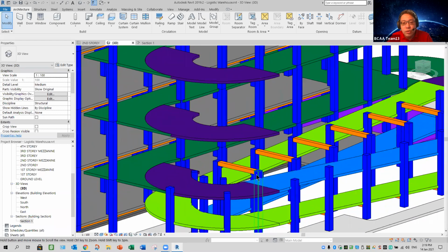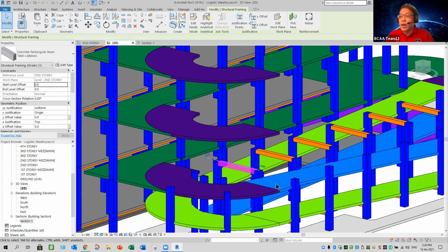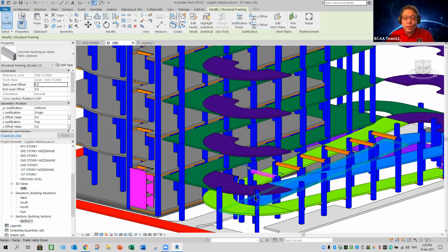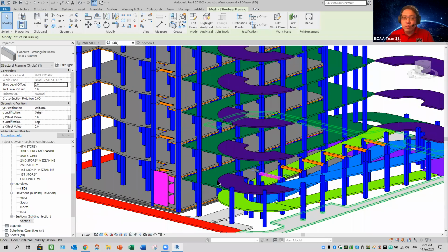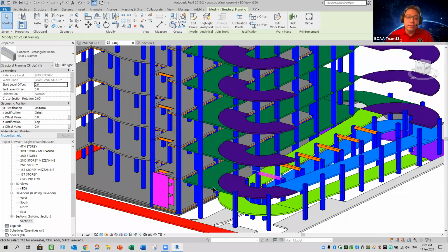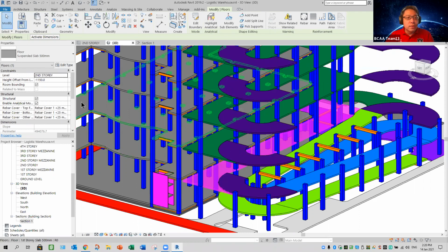The beam, based on the node, should be 1000 by 800, so-called the B by H, right? Now, the landing for the ramp should be flat, all right, flattened, same as this level. Now, this level, if you double check, is actually minus 1150, which is you take measurement from the second story.